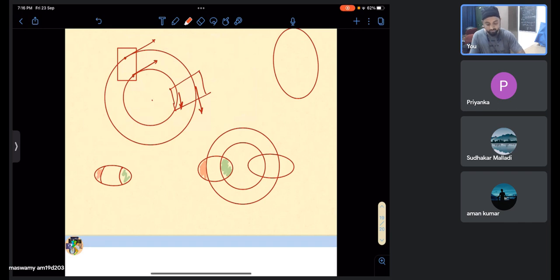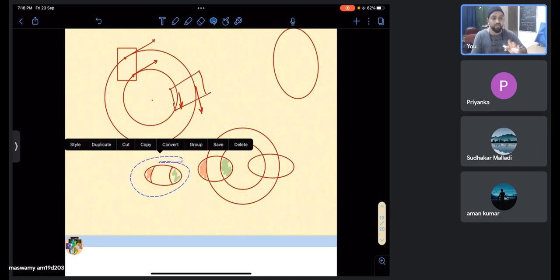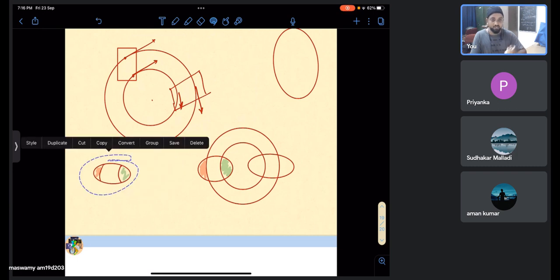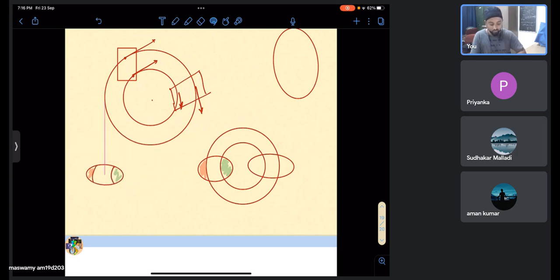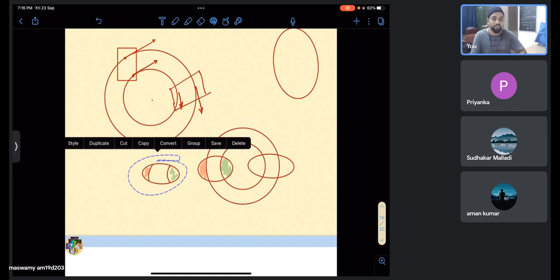Okay. So what this can be thought of is this translated to that point and then flipped by 180 degrees, rotated by 180 degrees. So in our lecture, what has been shown is the total motion can be decomposed as translation and rotation of 180 degrees. So general plane motion is decomposed into translation and rotation.